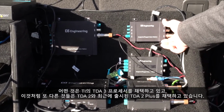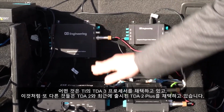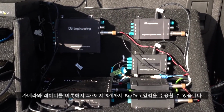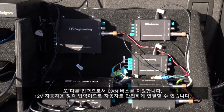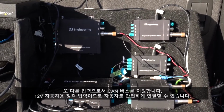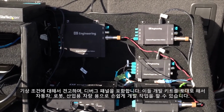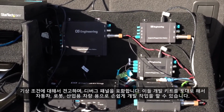Some are based on TI's TDA3 processor. Other ones, such as this, are based on the TDA2, and a recent addition is the TDA2 Plus. They can take anywhere from 4 to 8 SerDes inputs in, so cameras and radar. They also have other inputs, CAN bus, they're automotive rated parts. It's a 12-volt automotive input, so it's safe to put in a vehicle. They're weather tight, they have a debug panel. They're really good places to get started either on an A-sample or R&D projects on automotive, robotics, or industrial vehicles.